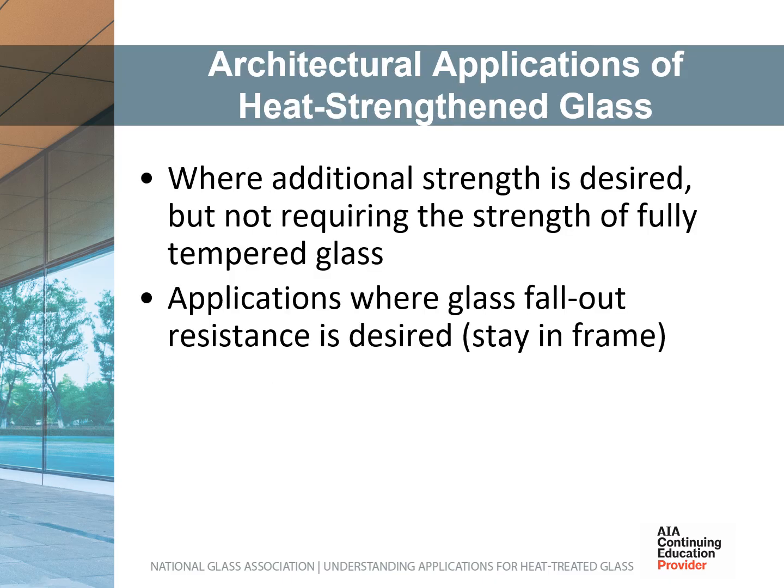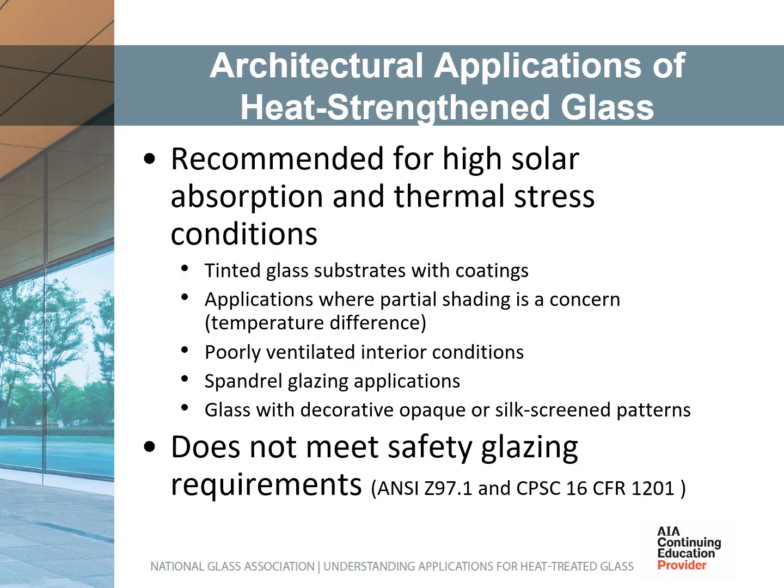Heat-strengthened glass will break similarly to annealed glass but offers high thermal and wind load resistance. The glass break pattern will typically prevent glass fallout because the edges will be held in place by the sealants, gaskets, and glazing material. Color, clarity, chemical composition, and light transmission characteristics of glass remain unchanged after heat treating. Solar and decorative applications work well with heat-strengthened glass products. Because tinting reduces the solar transmittance of glass and increases solar heat absorption, heat strengthening is sometimes required due to the heat buildup and resulting thermal stresses.